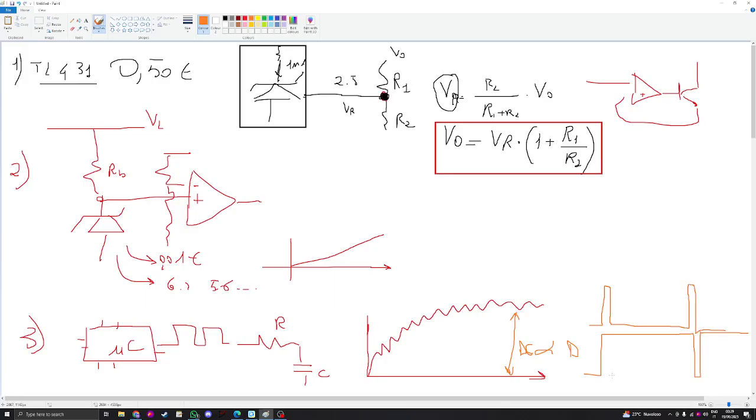And why is that? Because basically, the higher the duty cycle, the more voltage is constantly applied to the capacitor. That's it. So this is the first point. The second point is the ripple. The AC ripple basically depends on the RC. If your RC is more robust, then you're gonna have less ripple. But you have to pay a price, and the price is speed. Suppose we have the same duty cycle but a stronger RC, you're gonna have something like this instead. So you're gonna pay in speed.